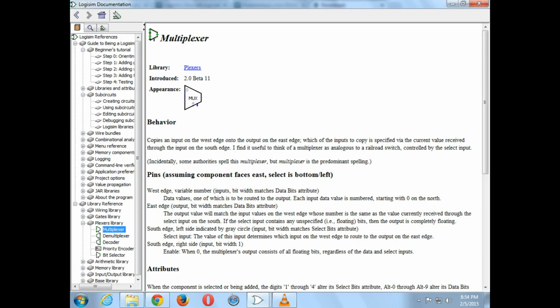All right. So a mux is basically a selector. You have multiple inputs, one single output, and a selection bit to basically specify how I should dial that switch. And then you have one enable, which basically says, yes, we do want to connect that particular input to the output, because it can disengage all the inputs from the output. So those are your options.